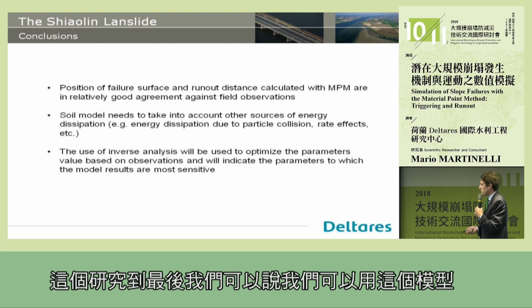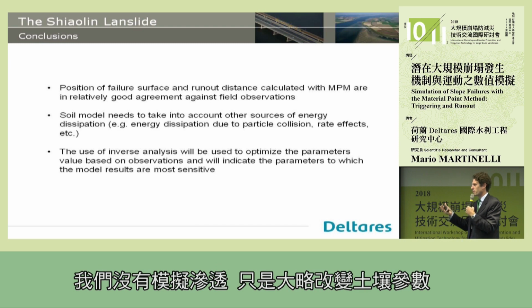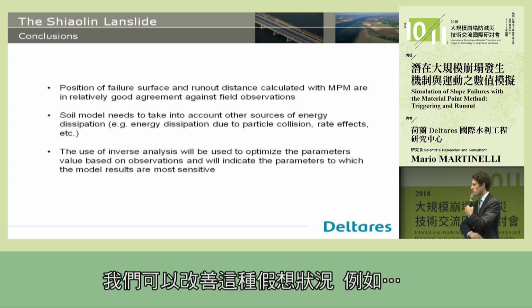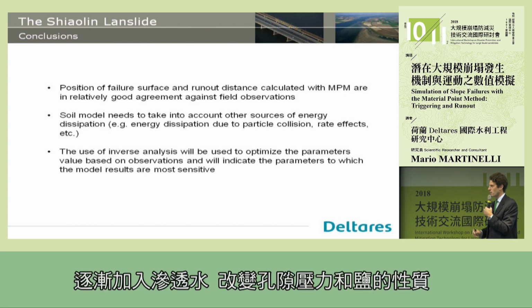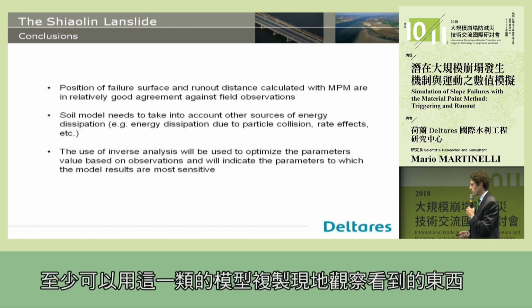Of course, at the end of this study, we said we could use this model to simulate the triggering in a very rough way for a couple of scenarios. We don't simulate the infiltration, but we just roughly change the soil parameters and we see the mechanism. We can improve that. We can improve this kind of scenario by, for example, progressively putting in some infiltration water and changing the pore pressure and also the soil properties. But of course, what we can conclude is that this method, or at least this constitutive model, can reproduce what we see in field observations.